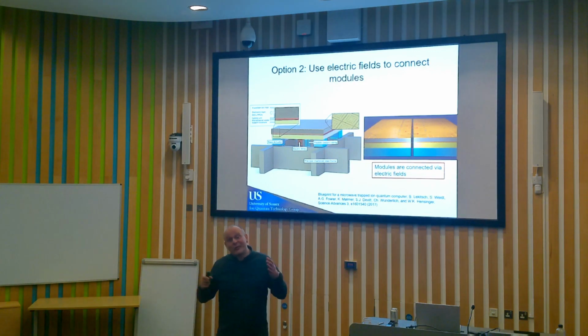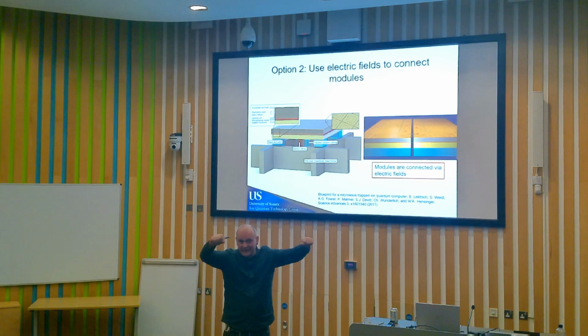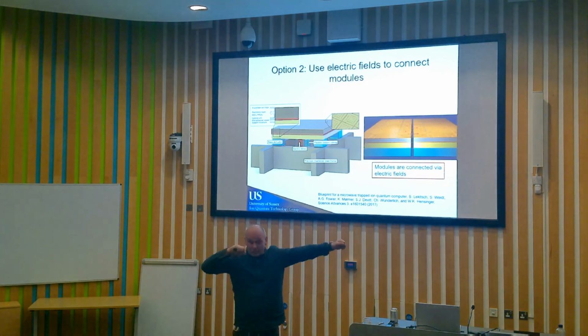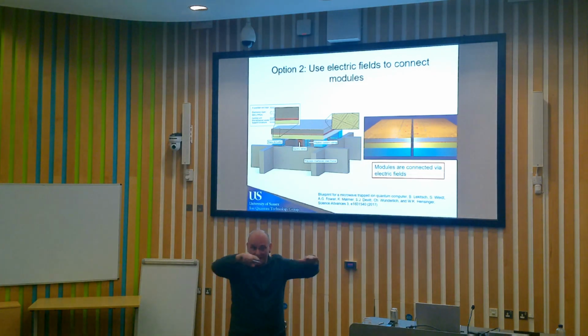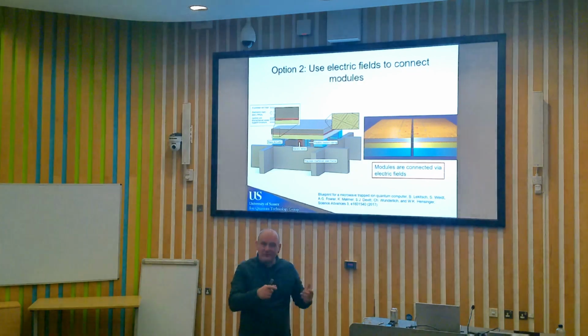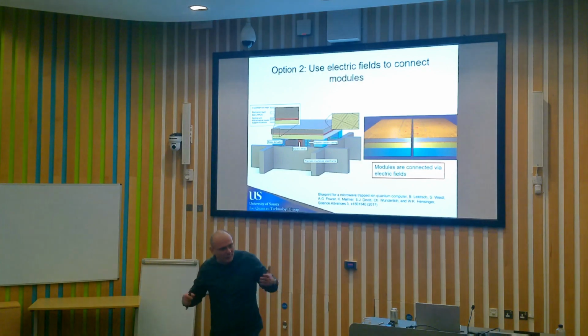It would not work so well because when you get interference, the microwave amplitudes wouldn't be exactly the same everywhere. So in one zone, a gate may take longer than in the other zone. Having reasonably homogeneous microwave intensity across the chip is useful, and that's something such an array would do really well. So we are interested in that technology, but it's by no means required.